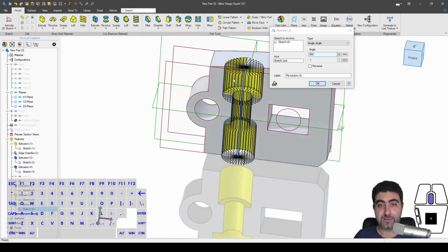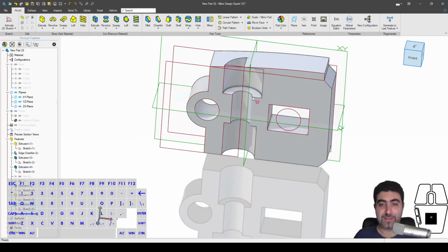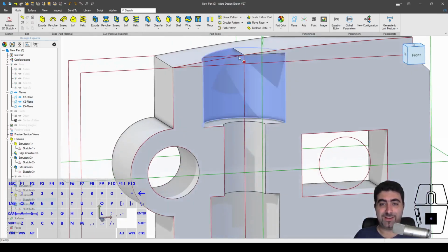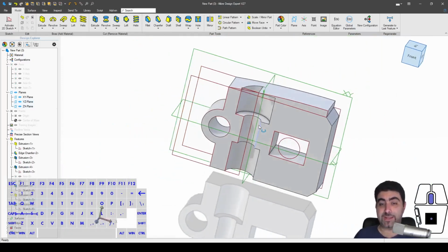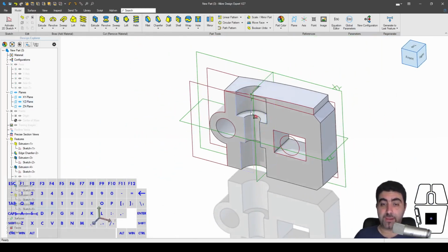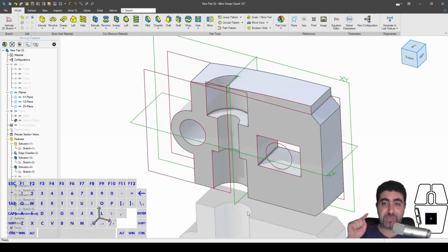Okay, the way I designed it wasn't very clever because it's not cutting. But you see what happened there, right? Because I was showing my sketches, I was able to click on that line and tell it to be the axis of revolution. So in Alibre, it pays to have your sketches showing.